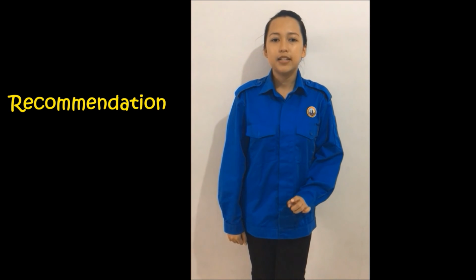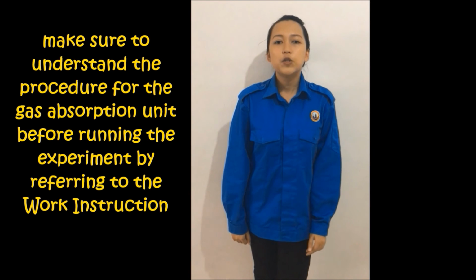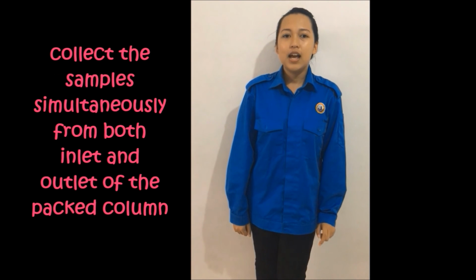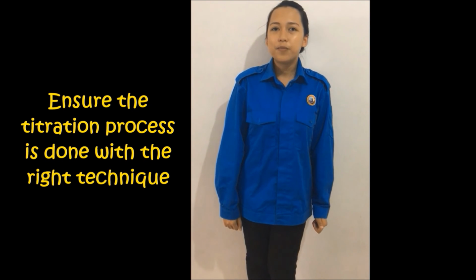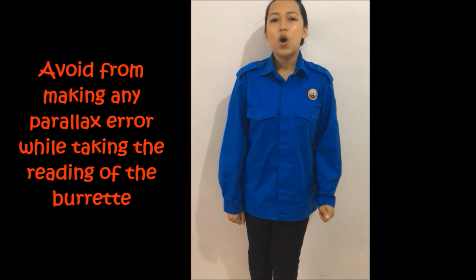Thus, it is recommended that before running this experiment, make sure to refer to the work instruction in order to fully understand the gas absorption unit. Next, collect the sample simultaneously from both inlet and outlet of the packed column. Other than that, ensure the titration process is done in a proper procedure. Lastly, avoid making any parallax error while taking the reading of the burette.